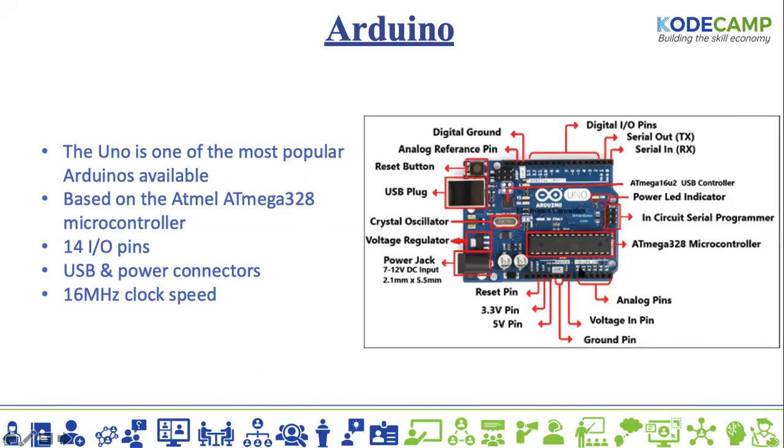Now these other pins are the analog pins from A0 to A5. They are basically analog pins used to send analog signals into the Arduino. Inside of it, there's something called an ADC. When one is sending an analog signal, it goes through an ADC, which is an analog to digital converter. That analog to digital converter is going to convert the analog signal that you just sent to a signal that the Arduino can read digitally, and then send it to the main microcontroller, and then the processing is done.